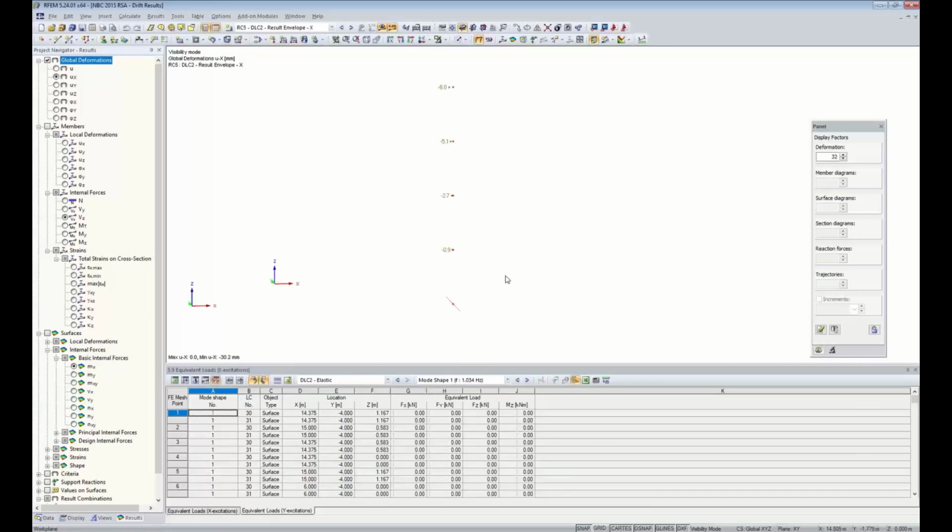So looking at the very bottom, of course, we have 0 deflection where our supports are. We look at the first story, we have 0.9 millimeters. And looking at the third story, we have 2.7 millimeters. So the inner story drift would be that 2.7 minus the 0.9. Taking a look at the story above it, the 5.1 minus the 2.7.